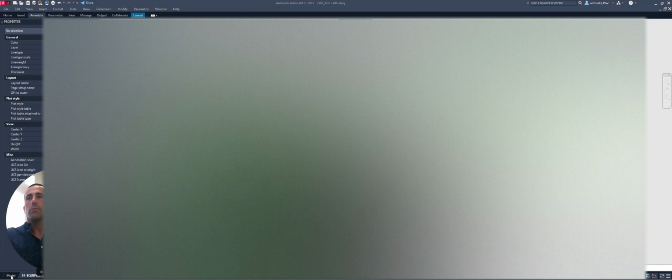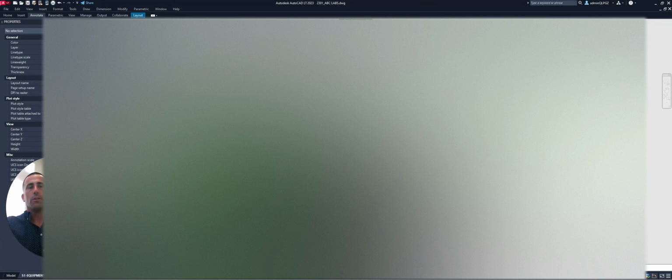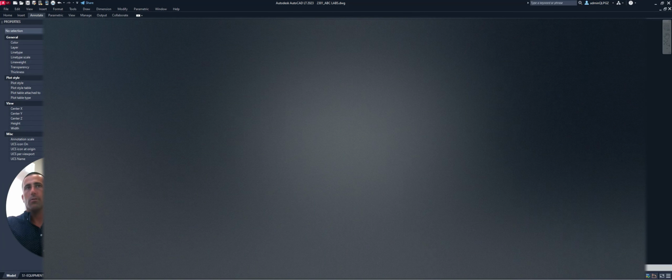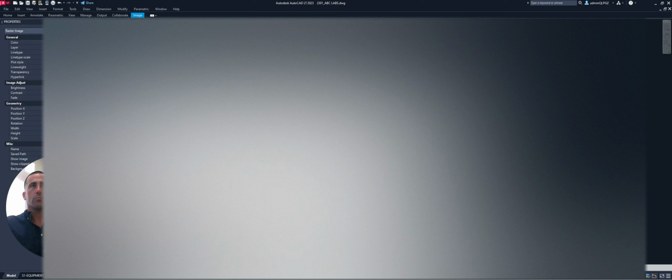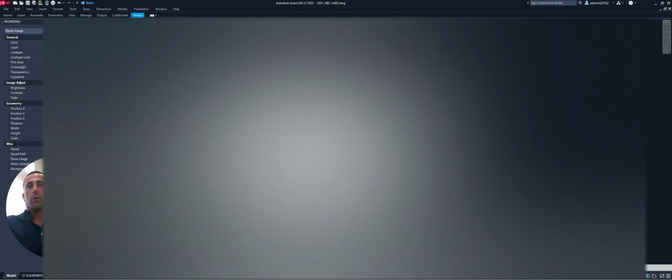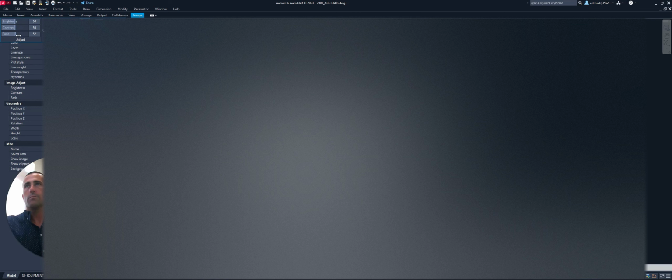And what I'm going to do is come to that image. Now there are other ways of doing this. If I had the AutoCAD file, I could paste in the AutoCAD file. Right now I'm putting in an image because that's just what I have. I prefer to put in the AutoCAD, if I have this that says AutoCAD, but I do not right now. I just have this image, so I'm going with this. I'm going to come to the image, fade this at about 50%, because I want the focus to be on the foundation information.